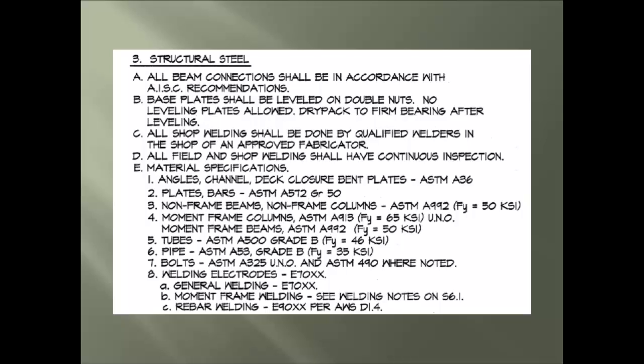We saw earlier in the seminar that the first rule was the approved specifications. And as the quality control and quality assurance professional, if steel is your discipline, you will need to review both of these approved documents for compliance. Some items of interest are base plates leveled on double nuts. All field and shop welding shall have continuous inspection.